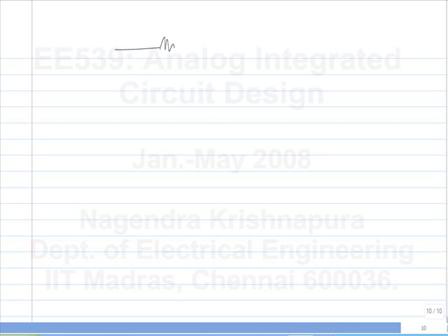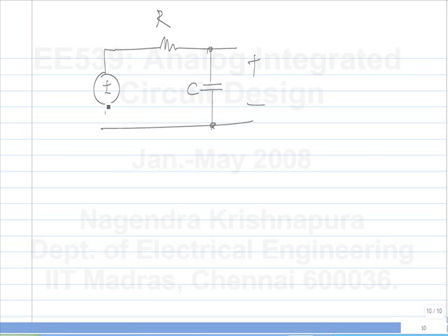We will continue the discussion of this in the next week, but please calculate the spectral density of noise in this circuit. So this is a first order low pass filter, we are all familiar with it. So this is V out, you calculate the spectral density of V out, and you also calculate the RMS value of V out because of noise.